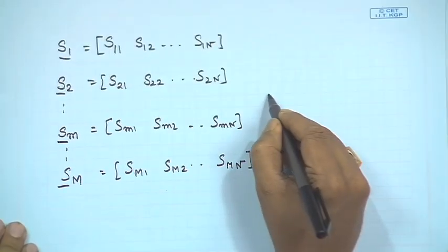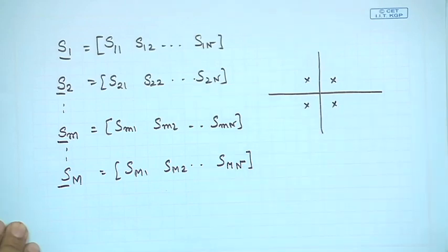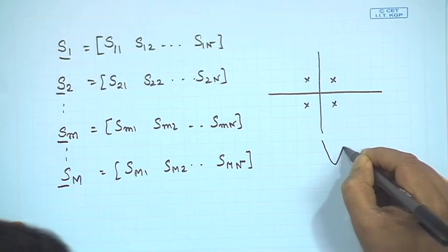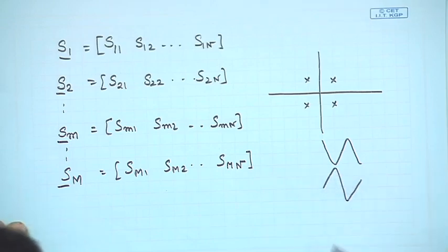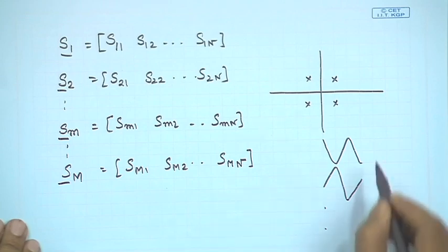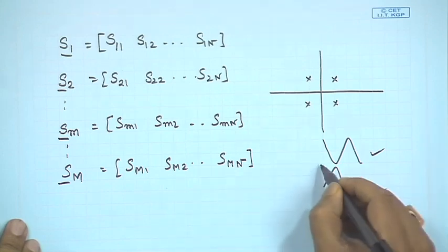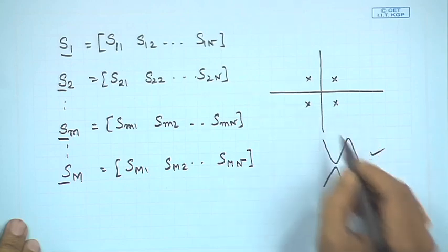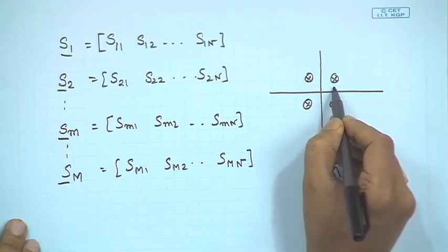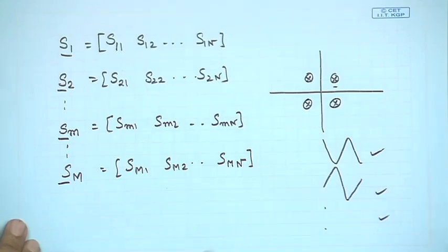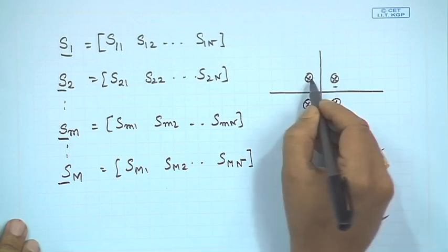For example, if I have QPSK, there could be a waveform like this, a waveform like this, and 4 waveforms in all. The detector has to choose one of these waveforms and identify that probably this was sent. It cannot say that something which is none of these 4 has been sent. In terms of baseband constellation, it has to select one of these options. It can't say that something in between has come, which is actually what the first part does. The first part projects the signal on the I axis and on the Q axis, on the basis dimension.